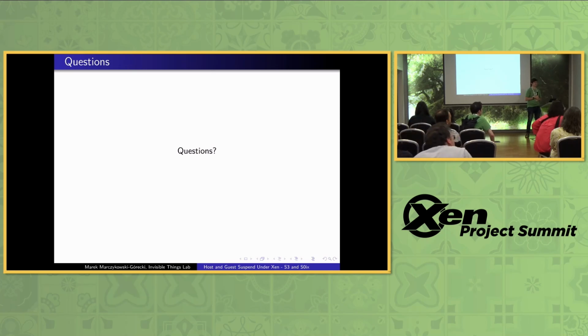So D3 holds a register in config space, isn't it? No, if the device is in D3 cold, you have completely shut it down, cut off the power. Yes, but putting it into D3 cold is still a write into its config space. But then how could you get it back out? The sequence is that you first put it in D3 hot, and then issue this magic sequence through ACPI methods that actually puts it into D3 cold. Okay, fine. It's an ACPI method, so we can still hook it. Yes, you can hook it, and you can actually probe for the state of the device by reading the GPIO responsible for asserting the reset and the power pins.